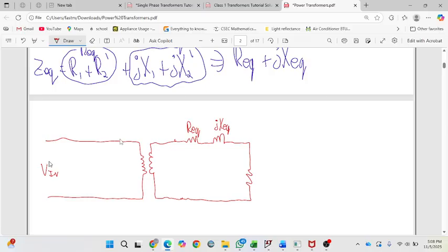Okay, so if you have your Vn here, we have a voltage here. If this is 200, you have no losses here, so this literally is going to be E1. Okay, and then once you use your turns ratio, you get E2. But now, because you have these losses, you have to account for all the losses in the circuit on this side. So this is I2 now, just keep that in mind. Once you have your I2, the losses across here will give you your V out.